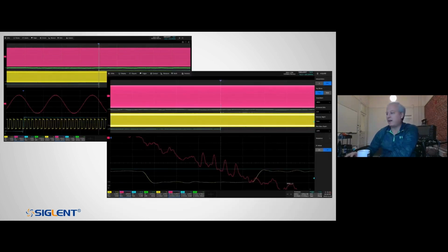Now we can really attack it by going from that display on the left to zoom in vertically. So now we've zoomed in vertically and we can see a series of pulses there invading our signal. So we can capture this and ultimately be able to correlate and determine the cause. So here, even though I've zoomed in horizontally 10,000 times, we still have enough sampling overhead to utilize a filtering mode to clean this signal. So I chose 1.5 additional bits here to get the best view.